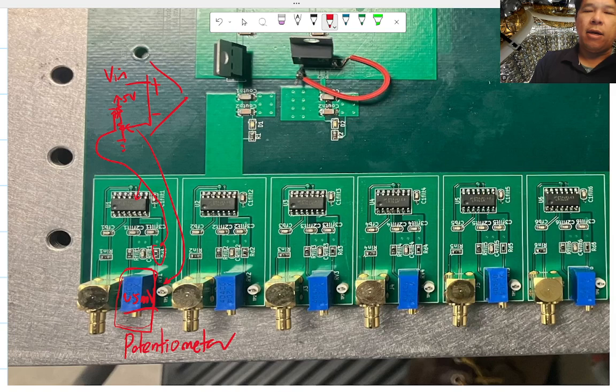And what happens is that as the signal comes in, it'll pulse, right? If we have something, the voltage is a function of time. It'll give you a pulse, and these pulses are maybe 10 millivolts in size. And then the comparator, since this is set to 5 volts with a threshold of 5 millivolts, which is actually not that low, it's up here, right? When it crosses this, it goes straight up to 5 volts.